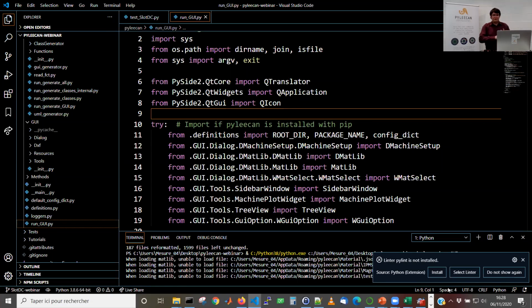Okay, so the question is, I made an axial symmetry copy of the slot. So first, you can do basically everything you want in Pyleecan as long as you provide the proper object with the proper bit geometry method. For instance, here I have a slot which is fully symmetrical, but I could have decided to do something else. And as long as I provide the full list of lines that draws the edges of my slot, it will be available in Pyleecan, even if it's not symmetrical. That's the first part of the answer.